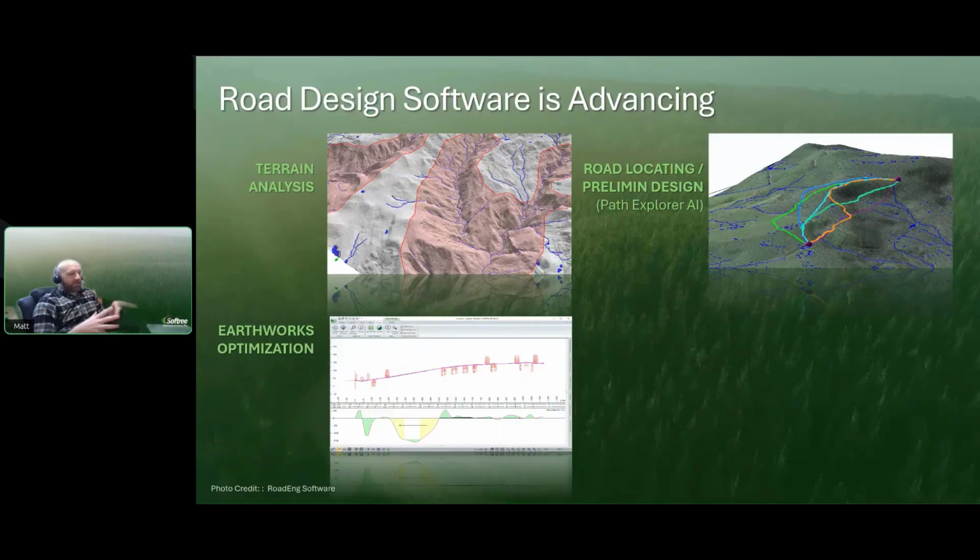And then taking it a step further in terms of detail, we've got our earthworks optimization stuff. So that could be just looking at the haul. So figuring out where cut material should be used as fill, and minimizing that haul distance is valuable. But we've, of course, backed that onto the vertical optimization stuff where we'll adjust the vertical alignment to further reduce material movement and handling.